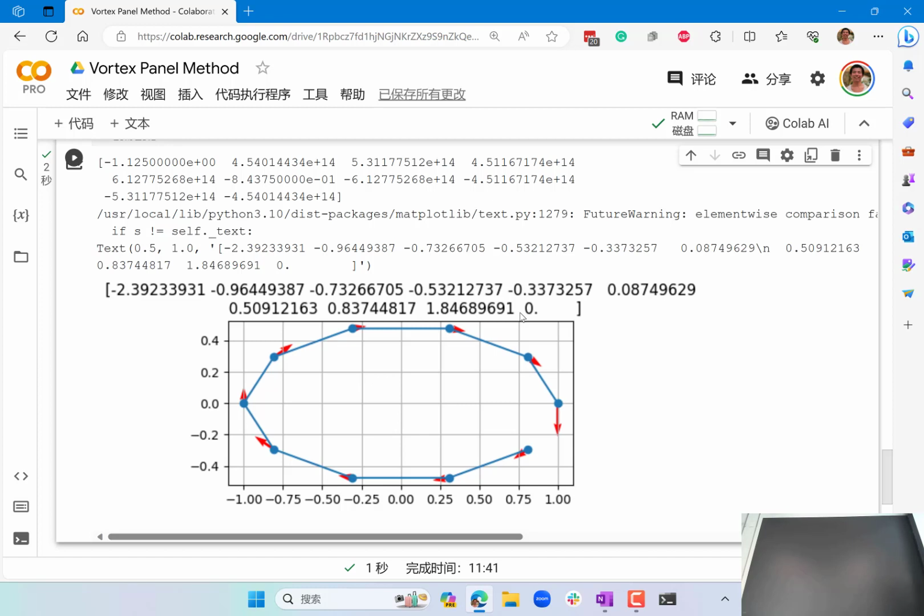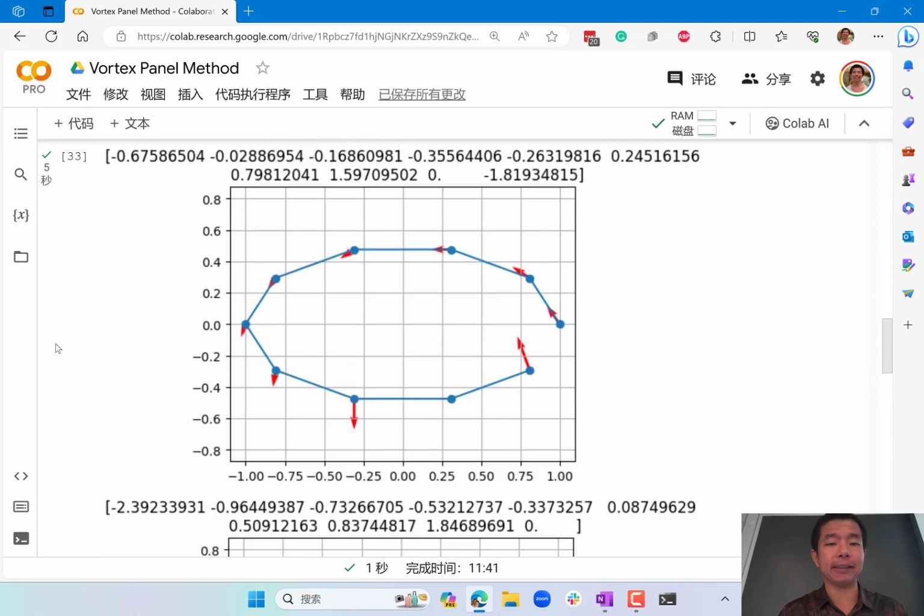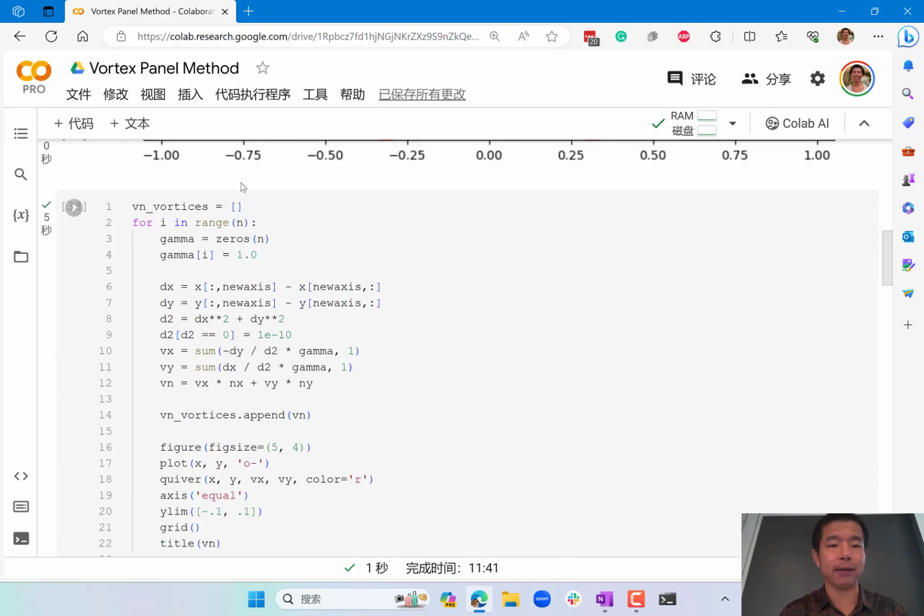And for a viscous flow, velocity that's very large at the trailing edge at a sharp point is going to separate. We are going to say more about this in the viscous flow section, but the flow separation puts another constraint on what the circulation, what the vorticity distribution on the solid geometry has to be. So let's add that onto the set of equations and solve them a little bit differently.